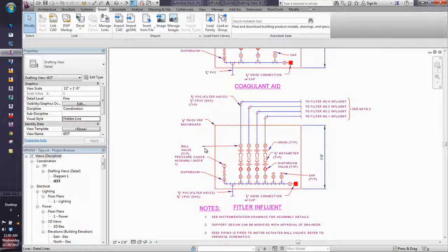What would happen if you inserted a drawing that had a layer in it, but the drawing you were inserting into had the same layer? What takes precedence, the drawing you're inserting or the one you're inserting into? The one you're inserting into. So it works the same way in here. If you have that line style already defined, then when you insert it, it's going to assume the property that you want in here. And that includes things like the line weight.